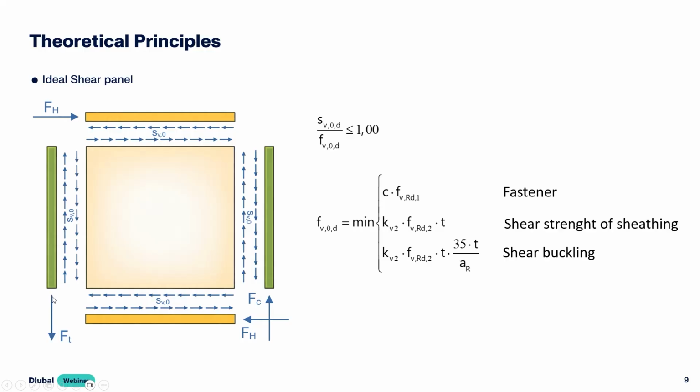We get here our tension forces and here our compression forces. Here we need to place some hold down, and here in this compression area, of course, we need to make sure that the bottom plate will be able to handle the compression perpendicular to the grain.